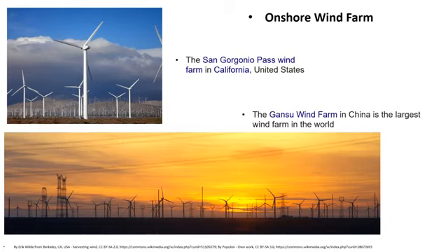The onshore wind turbine installations are generally built in hilly or mountainous regions and tend to be on ridges, generally 3 kilometers or more inland from the nearest shoreline. This is done to exploit the topographic acceleration as the wind accelerates over a ridge. The additional wind speeds gained in this way can increase energy produced because more wind goes through the turbines. The exact position of each turbine matters because a difference of 30 meters could potentially double the output. This careful placement is referred to as micro-siting.